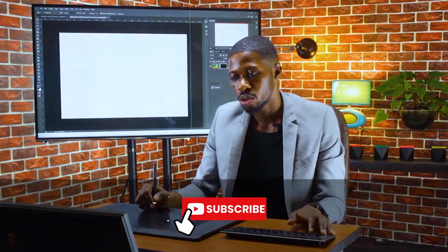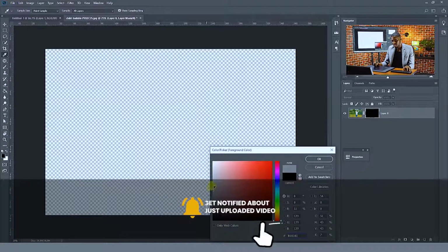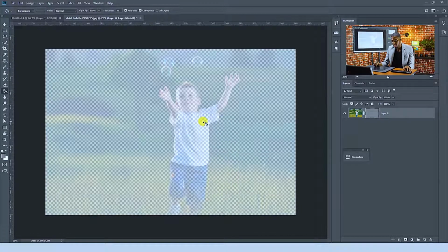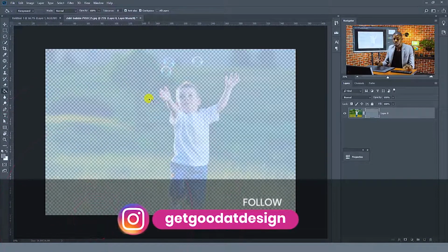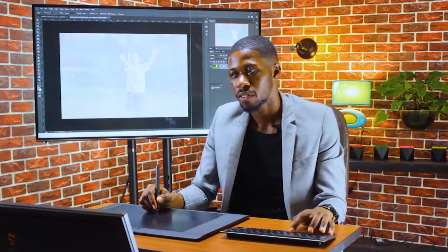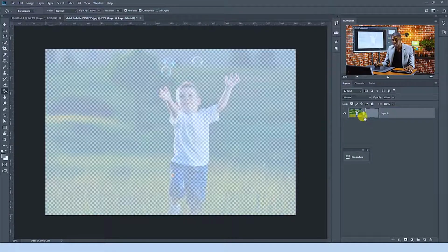You can also use the paint bucket tool to add a gray layer mask. Say we use 50% gray, if we use the color picker and we paint with gray, you can see that the image is partially hidden. So that is how to use the paint bucket tool. And always make sure that you have the layer mask selected, not the image. To make sure that the layer mask is selected, you will see there's a white bounding box around that box. So always make sure you have this box selected.